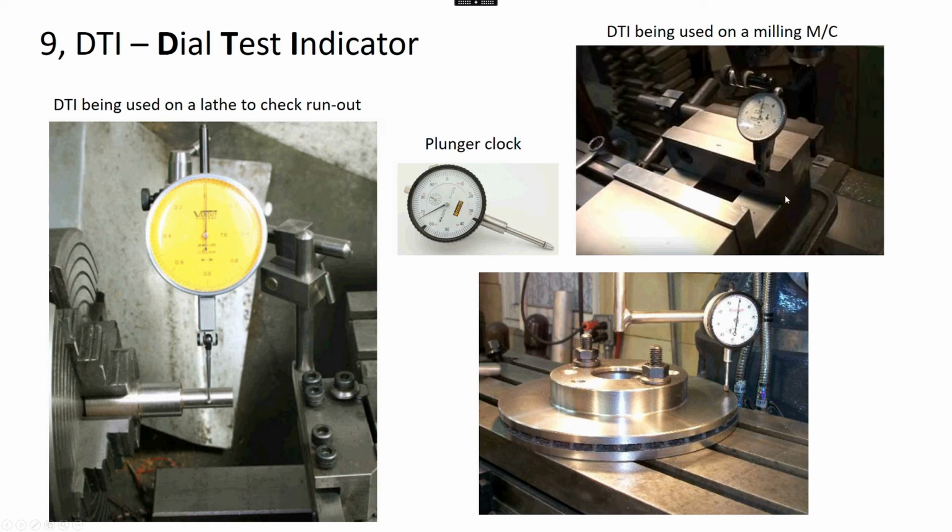You can test it with like a thou feeler blade or something in here to make sure the face you've machined is up against this jaw properly. And then you mill the top again, and then you've got a face that is square, and then you can just mill the other two sides. But using the bar helps to make sure you keep the part square.